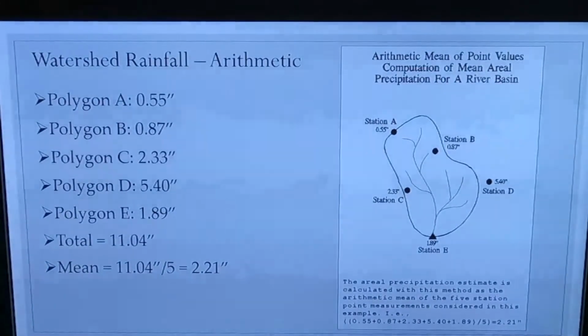This goes for irrigation as well. You need to know how much you're going to receive in acre inches, so that when you go to apply the water, you're not over applying. And you need to know how many gallons are in an acre inch, and how much water is needed, and there are going to be some recommendations. So this stuff is going to apply one day. You're going to look back and go, oh, I remember Natchez told me this. I'll go look back at my notes. It's just area over depth.